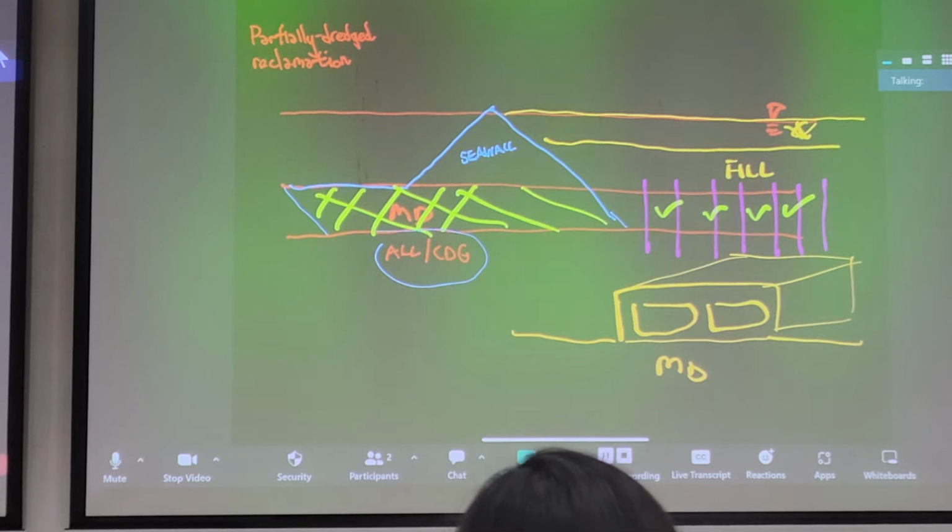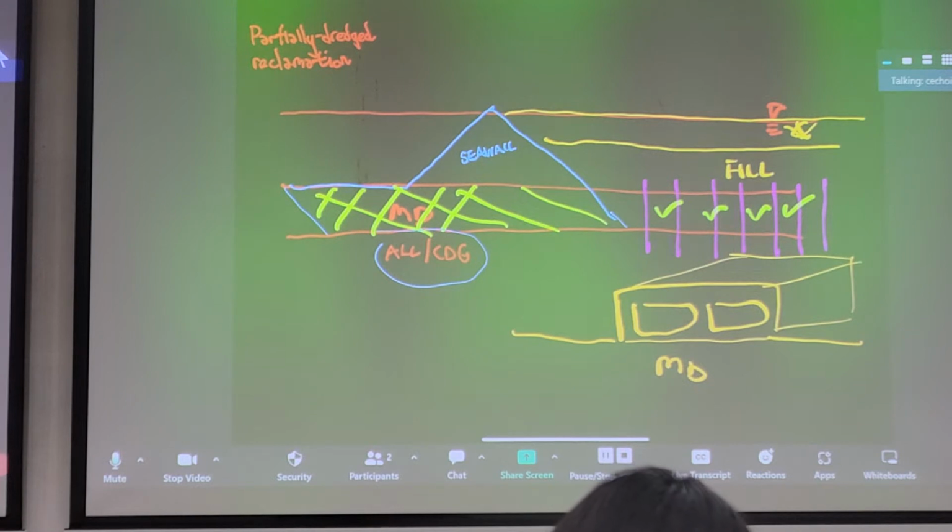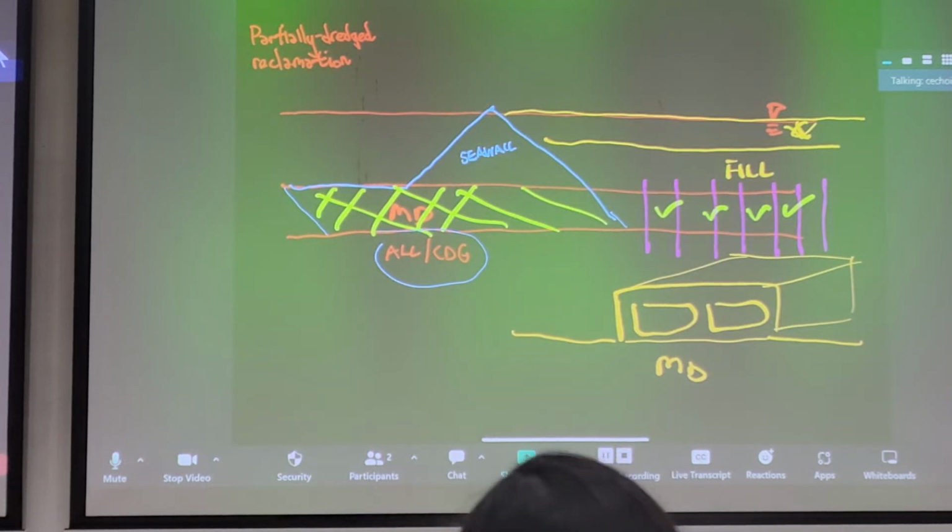So bear in mind that we're still producing waste mud from dredging various applications in Hong Kong. In fact, this waste mud could be useful, right? So instead of trying to just dump this waste mud into waste pits, other regions around the world, for example, in Japan, they have some quite interesting approaches where they take this waste mud, they mix it with a binder, for example, cement. They inject compressed air in it to mix it up.